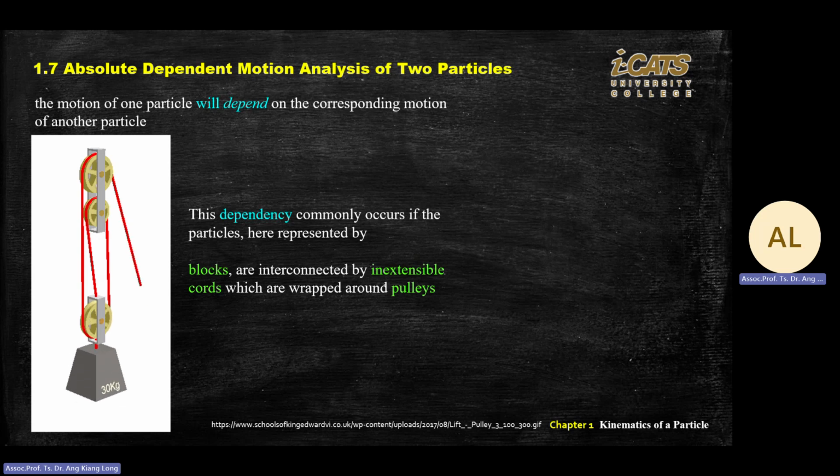One is pointing towards the point, or from the point pull down. Or you can draw a dotted line like this and put the arrow above, along the line. Why? Because in statics, all forces can transfer along the axis of action.